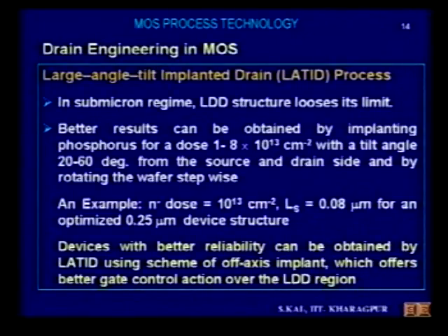So these are the two drain engineering methods by which the short channel effects can be improved. One is the LDD structure, another is the LATID structure. In the next class, I will discuss the LDD structure of MOSFET, how the LDD structure is formed, and the details of the process sequence of the LDD MOSFET. Okay, let me stop here.